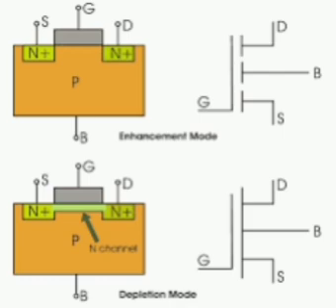JFET parameters in the saturation region: current through FET is given by IDS equal to IDSS into (1 minus VGS by VP) whole squared. IDSS equal to saturation current at VGS equal to 0. VP means pinch off voltage. IDS means saturation current at any VGS. IDS varies parabolically with respect to VGS.